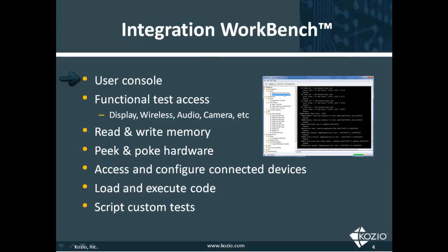From here, you'll have access to a test menu, as well as a command line interface to VTOS. Functional tests are run with the click of a mouse button by selecting them from the test menu. From the command line, you can read and write memory, peek and poke hardware, access and configure connected devices, load and execute code and tests, as well as create and execute custom test scripts.